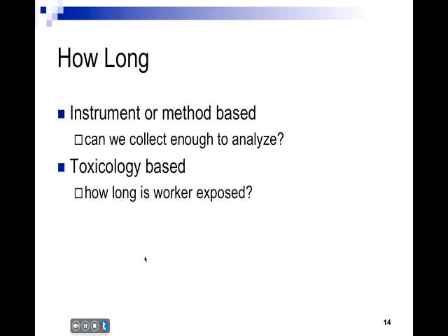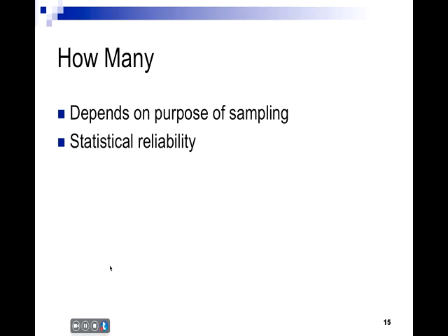If you're sampling very low air concentrations of contaminant, you have to collect enough on the filter that the laboratory can tell you if the chemical is present. So finding out how much you need to collect will help determine how long you need to sample. Or alternatively, you could be just worried about a toxicology-based type of sampling, and so you would be interested only in what worker exposure is. So you have some choices that you can make on how long to sample.